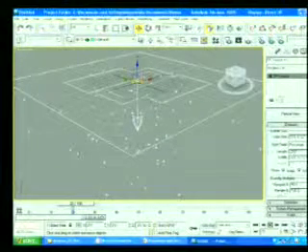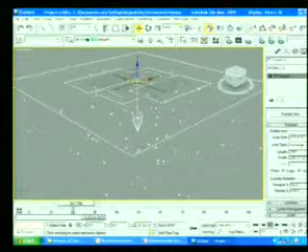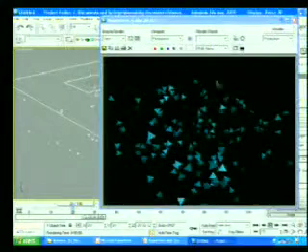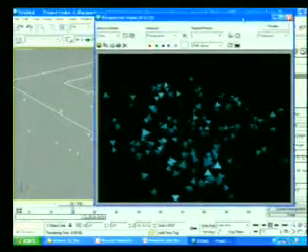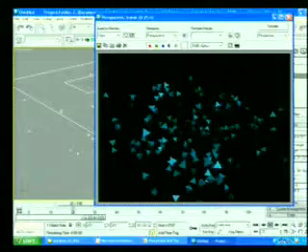This is the viewport settings, that in render we want 100% and in viewport we want to see these particles 50%. If we render this, we get the output like this.